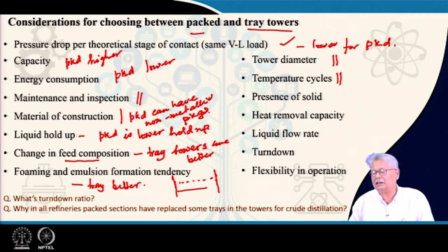Usually, if you are having packing of a brittle material, the packings start crumbling. This is particularly true if you are using some brittle material like ceramics as packing. Sometimes even the carbon rings crumble down.